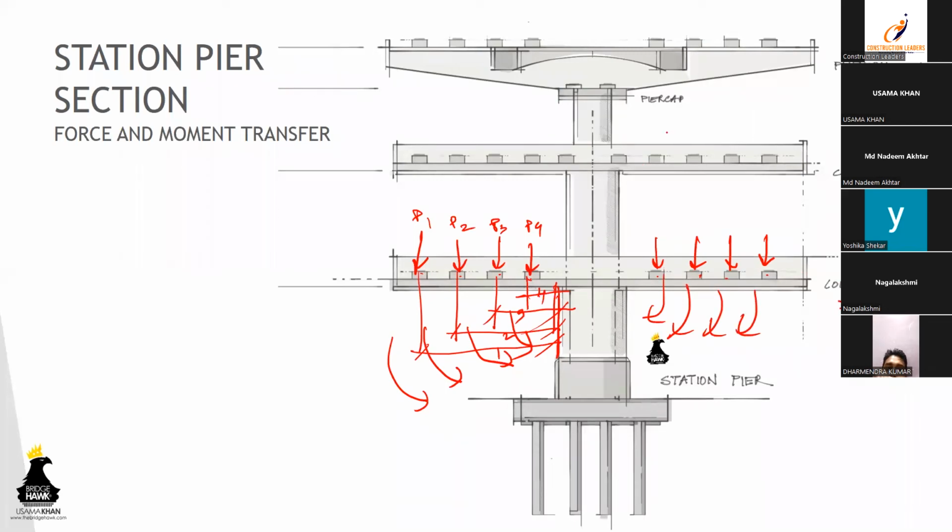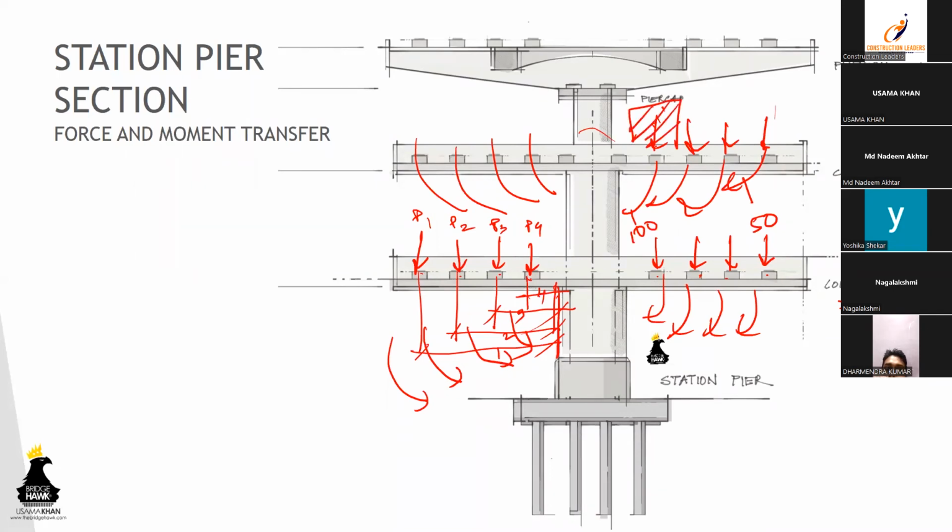This is level 1. On level 2, a similar case would follow. We'll have moments. This would be an increasing magnitude, or it might also decrease. The lever arm is not the only concern. Of course, if the lever arm is more, you'll have more moment. But it is possible that the moment over here is maybe 100, and over here it would be 50. Why? Because it is not only a matter of lever arm. Over here, maybe we have some furniture or a machine like this, so the SIDL load is more. So the point load itself is maybe 1000, and even though the lever arm is less, we'll have a higher moment. And we don't have any loads over here, so the dead load and the live load will not be creating a sufficiently high moment. So it is highly possible that the moment from this is less than this, regardless of the fact that the lever arm is less.